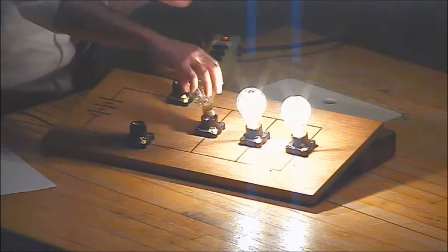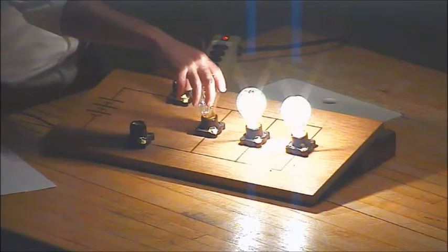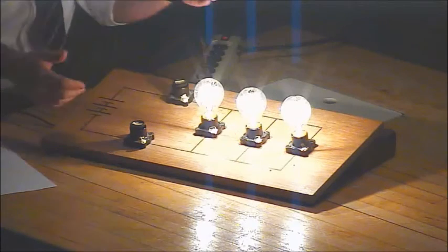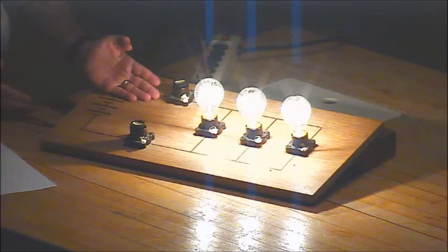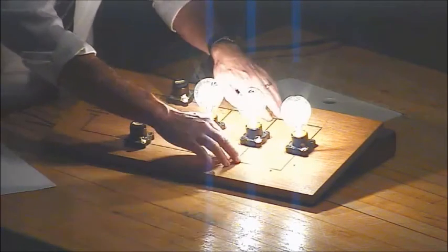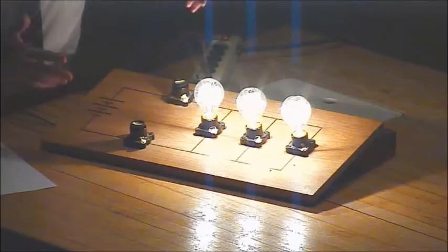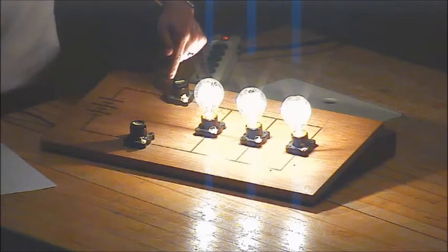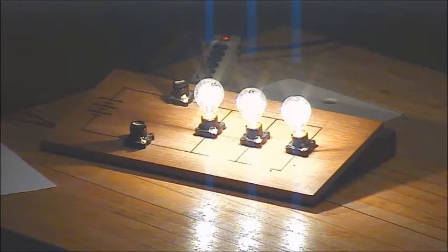In fact, here's where it looks like you're getting free voltage. Look, I can make three bulbs all really bright. All three bulbs are seeing 120 volts because the power company is doing their job. There's 120 volts up here and ground down here. All three bulbs are seeing 120 volts, and all are nice and bright, but I'm paying for it because each one is drawing current. And so I've got a lot of current. I'm pulling a lot of current right now.